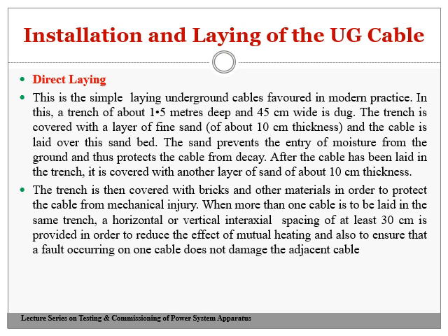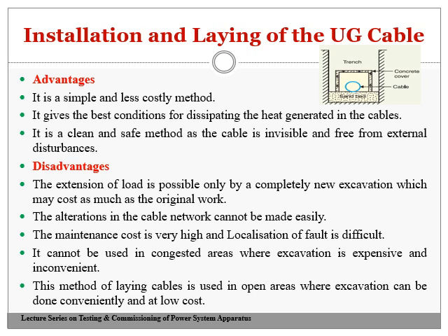We'll see that this method is simple. The trench is there, then we have a sand bed, then we keep the cable, and once again we have a sand bed above that cable.